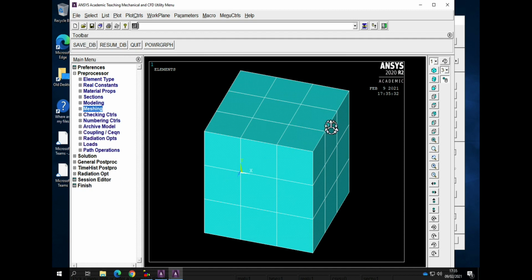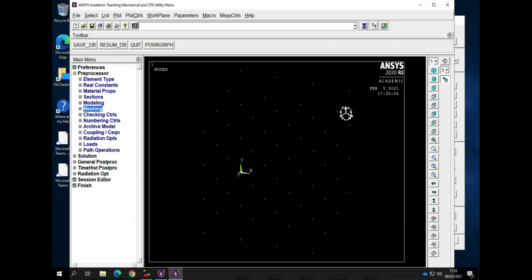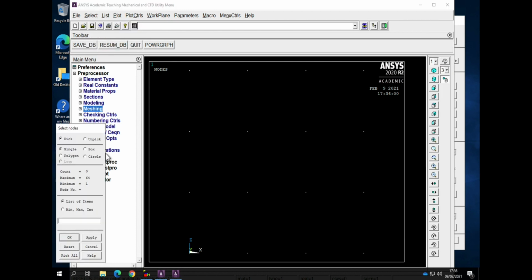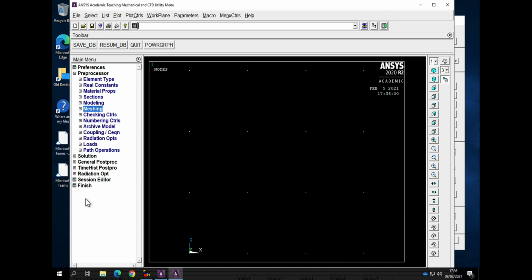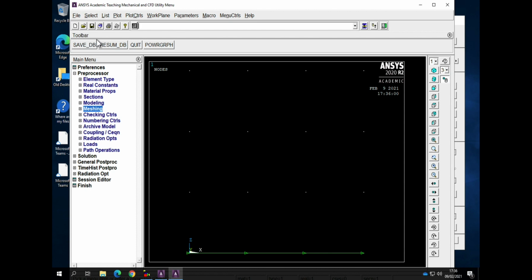So remember, I now need to add some electrodes on the top and bottom in the poling direction. So let's get a nice view, there's the Z direction. So I'm going to put an electrode at the bottom, electrode at the top. So select entities by nodes as a box. So couple set 1 will be the electrode at the bottom. And so I couple those, CP 1, volt, all. So in the degree of freedom volt, these are all coupled.